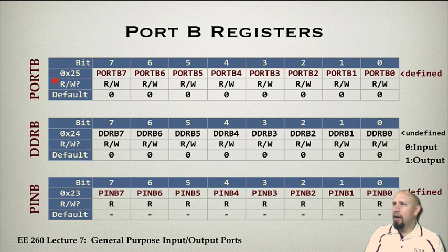So I can say PORTB equals something and actually assign it a value, and that would be comparable to writing that information to port B. Also, each of these pin numbers is defined in the Arduino IDE. That's another bonus you're getting directly from me: these names are actually defined. I don't have to do an include for a header file that has these names. When the compiler runs, there's already a header file defined that it accesses, and I don't have to refer to it directly.